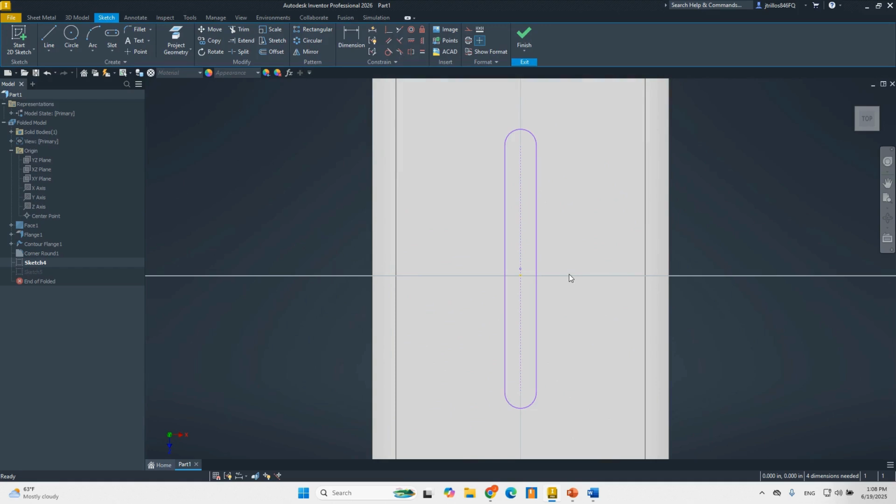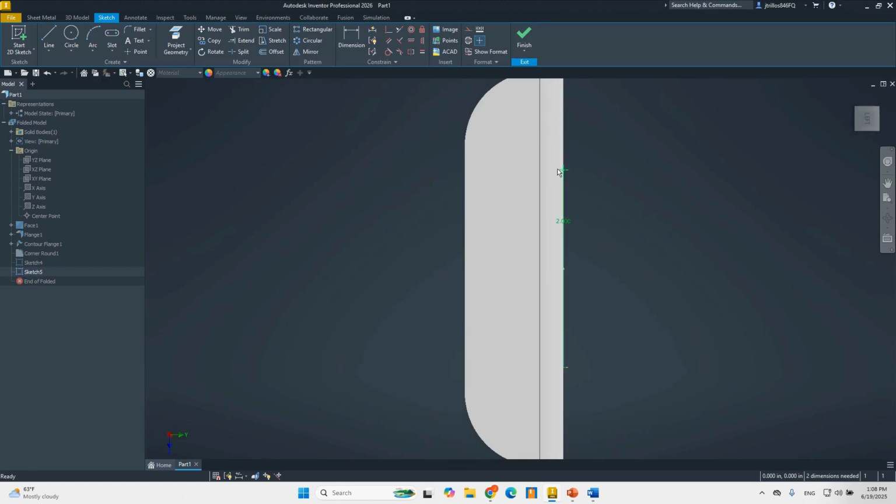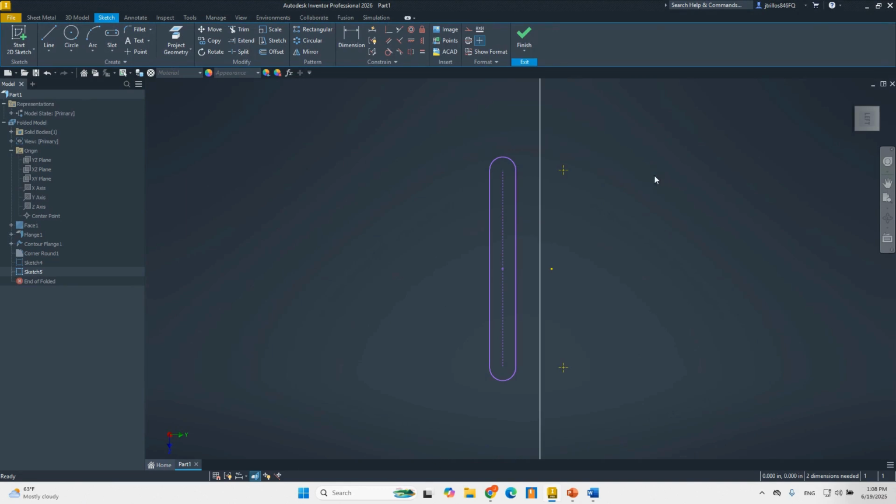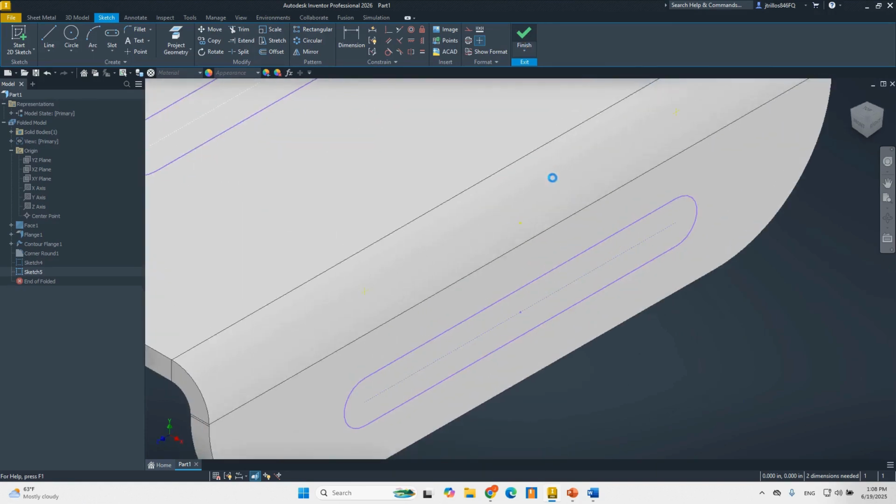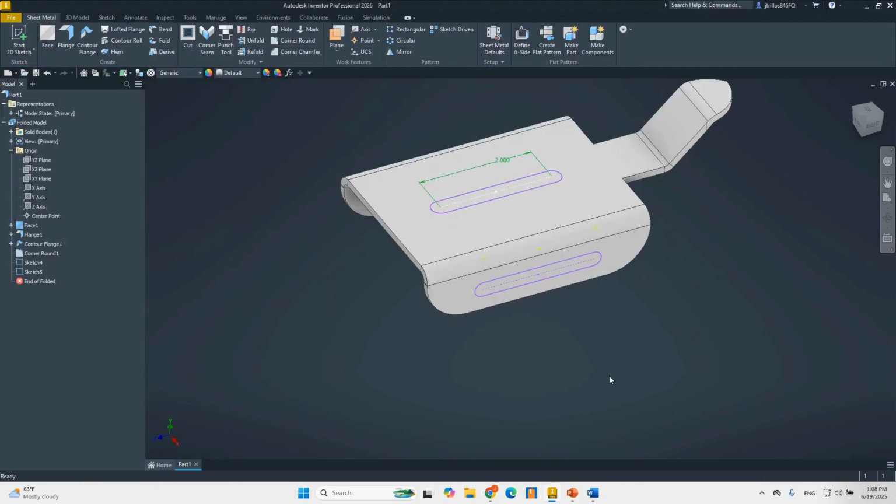That's going to jump to the previous sketch. Okay. So that way I don't need to worry about finishing the sketch, making sure that the entities are well set. I can go ahead and modify this, right? And just double click on the other one, and all the entities are going to update automatically. Okay. So that means much faster work. That means more reliability between the sketches. Basically, that's going to enhance my user experience.